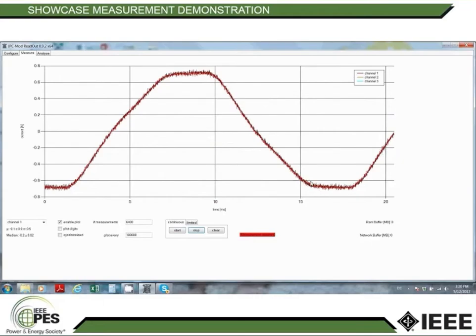Now with 64 oversampling rate, the distance between 2 measurements here on the screen is actually 3.2 microseconds. Before, with 256, it was 12.8 microseconds. You can simply calculate that by dividing the oversampling rate by the frequency of 20 megahertz.